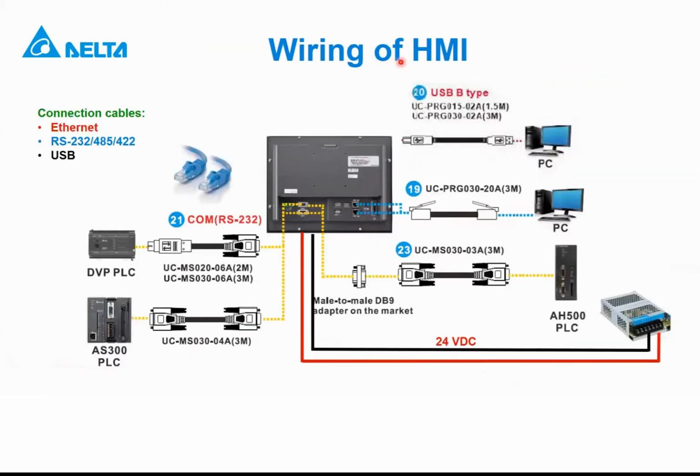In terms of programming, you can program the HMI with different cables. Virtually every port on the HMI can be used to program the HMI. In other words, if you have written your application for your machine, you can use any of these ports to download to the HMI. If you have Ethernet ports on the HMI, you can use an Ethernet cable to download. Also, if you have an Ethernet controller, maybe a PLC that uses Ethernet, you can also use the Ethernet cable to communicate with the PLC.